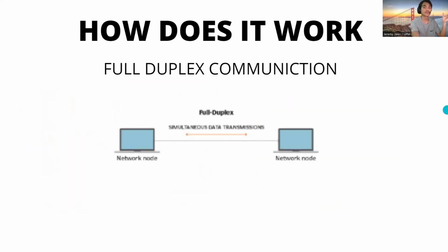So how does it work? Unlike wired intercoms that are usually half duplex, our intercom telephone is using full duplex communication. It has more than one pair of wires that is used to both transmit and receive. This means that both parties can talk at the same time, or in more technical terms, both parties can send and receive audio signals at the same time.